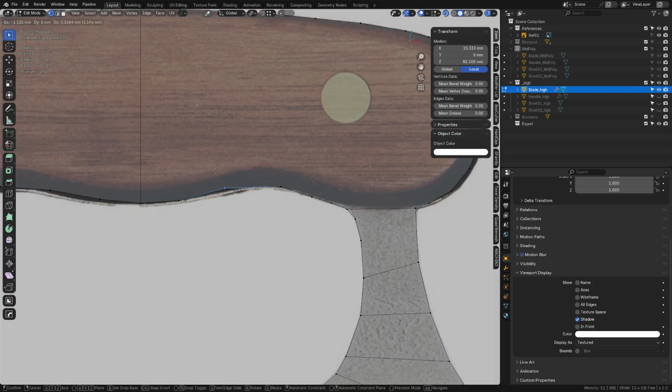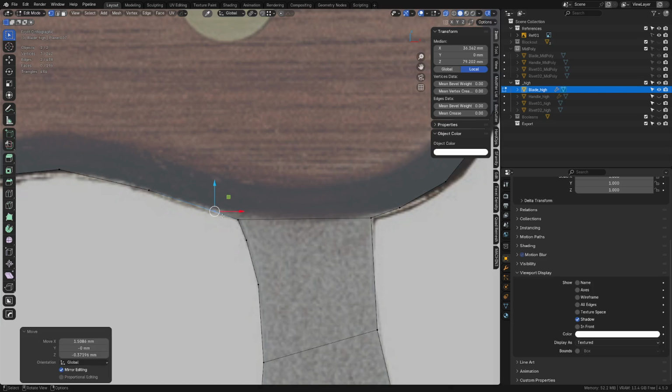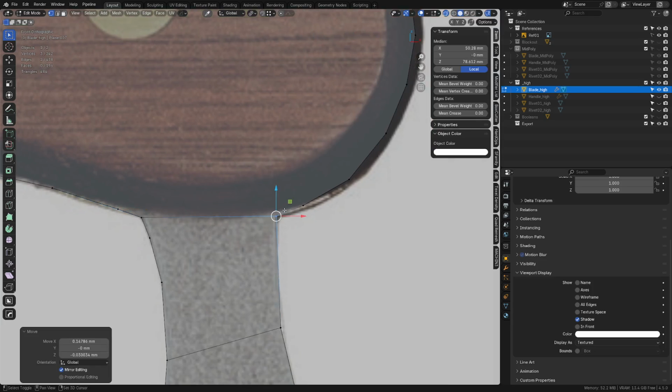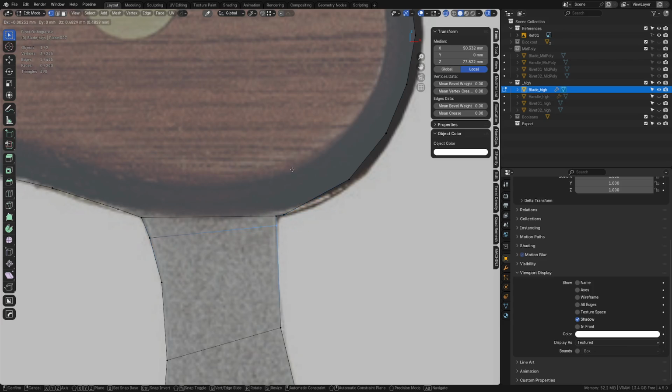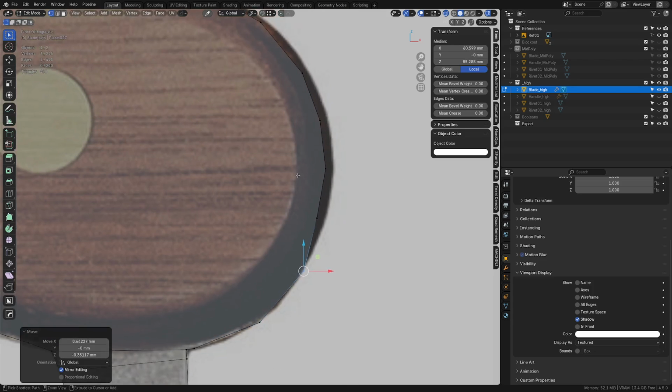But yeah, now we can get in here. We want to balance things out where they're evenly spaced, unless we're doing like a holding edge, right? You can see here, that lines up like that. And we want to control this bevel here. And this one over here, you can see we're going to need to hold it sharper. So we can actually bring this in quite a bit. We can press K and C and cut through. And we can kind of pinch that area a little bit like that, and then readjust all these if needed.